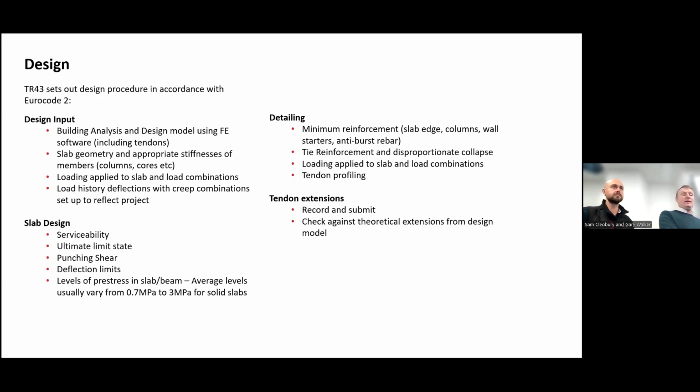So we'll model that slab with the correct geometry and appropriate stiffness for columns and cores. Make sure that we're modeling the structure properly and getting the correct analysis results. And we'll put the load on the slab that the structural engineer gives us, or the contractor says is what's going to be applied to the slab, and we'll do that in load combinations as set out in the code.